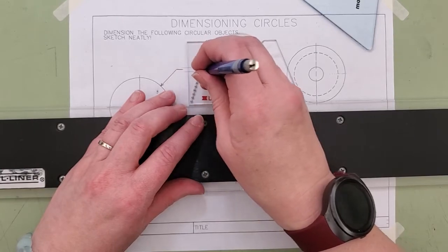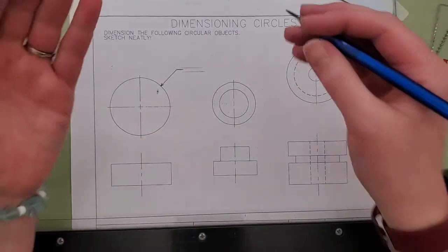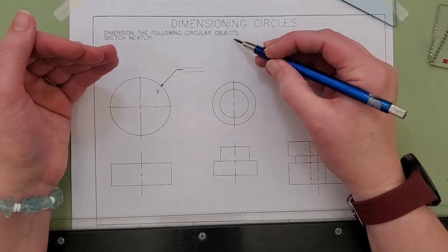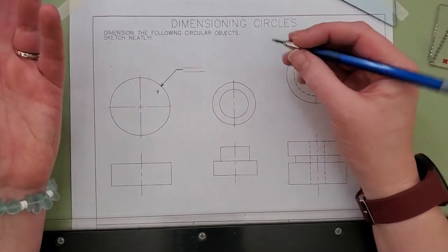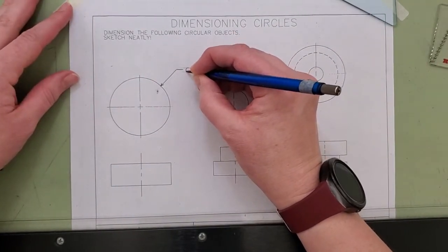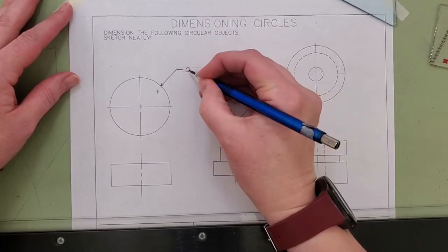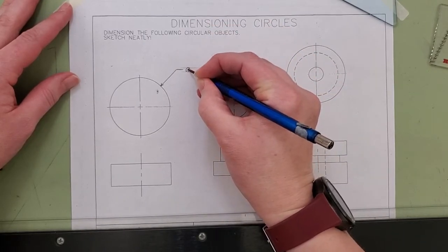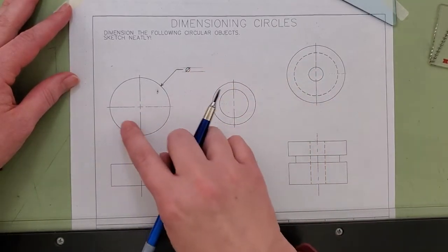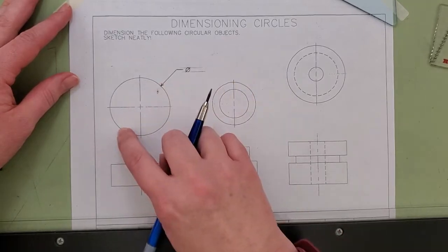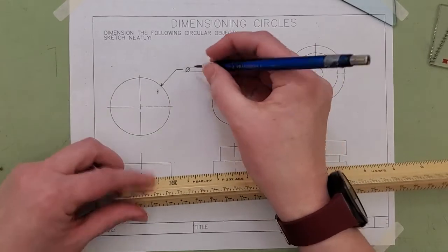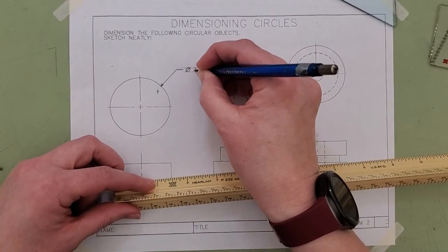1/8 inch lettering size. Okay, when we're dimensioning circles, we use diameter. When we're dimensioning an arc, okay, we would use radius. So I'm going to be getting the diameter of this cylinder, so I'm going to use the diameter symbol, which is a circle with a line that goes all the way through it, okay, from one end to another. That gives me the total diameter, saying the distance between this end and that end. So I'm going to take that measurement, and it's 2 inches, so the diameter equals 2.